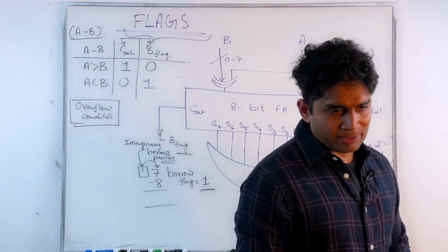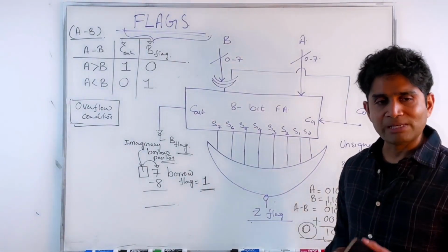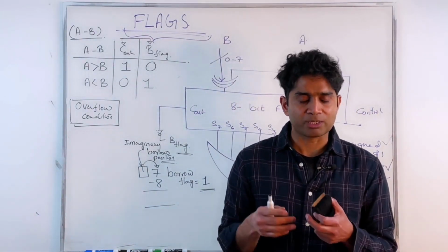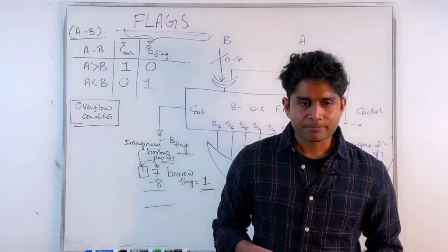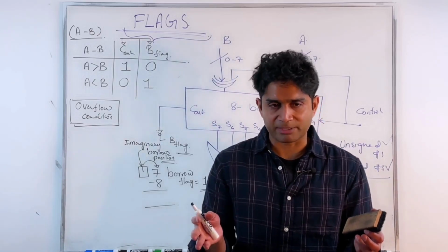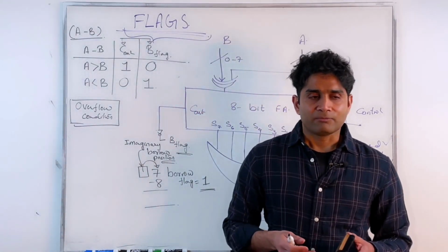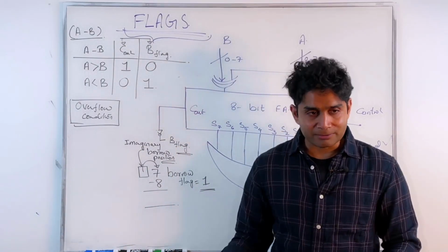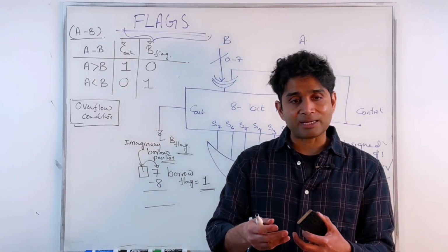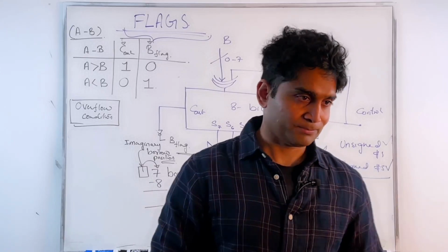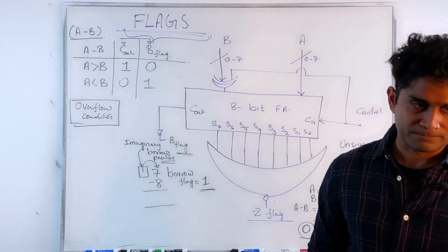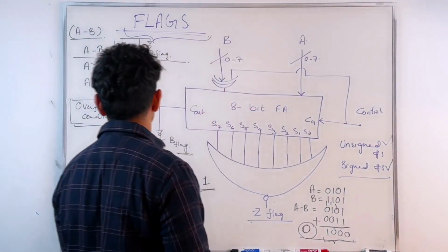When I'm working with binary, with these digital systems, I'm limited in size by how many bits my memory location can hold. If I'm working with 16-bit memory, each memory location can hold 16 bits. That's it. So my numbers can be 16 bits long, not larger. When I'm trying to add two 16-bit numbers together, the result can sometimes exceed 16 bits, which results in what is called an overflow condition. I need a mechanism to check for the overflow condition.